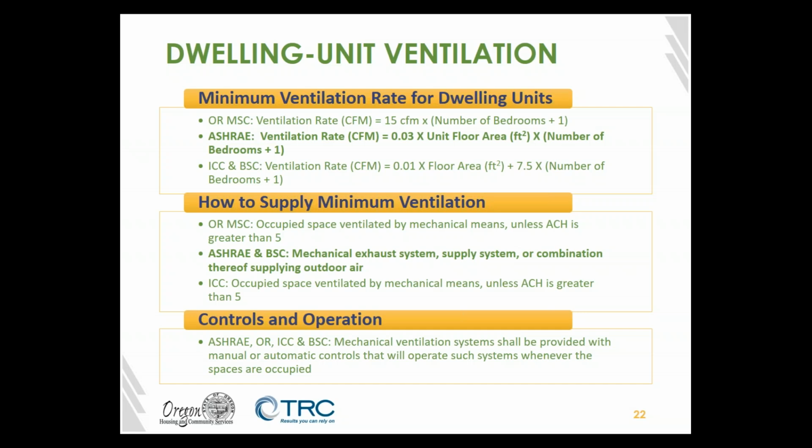The next is that they describe the how, whether you're going exhaust, supply, or balanced, and the differences between those, and how you have to tweak locationally where it goes and the rates themselves depending on your choices there. And then it also talks about controls and ensuring that these controls are operating whenever the spaces are occupied. So this is not spot ventilation, right? This is intentional, continuous, deliberate ventilation.